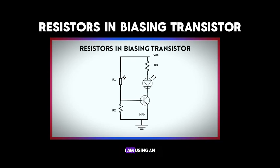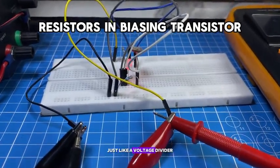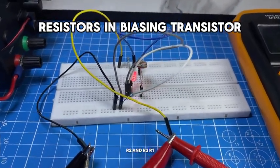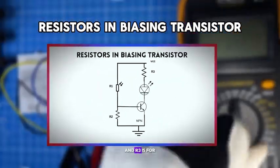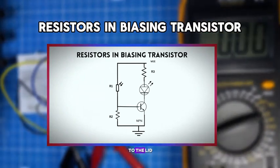So in this circuit, I am using an LDR to bias the transistor together with other resistors to make the circuit work just like a voltage divider. In the circuit, we have R1, R2, and R3. R1 is the LDR, R2 is to make a voltage divider, and R3 is for limiting the flow of current from the positive input to the LDR.